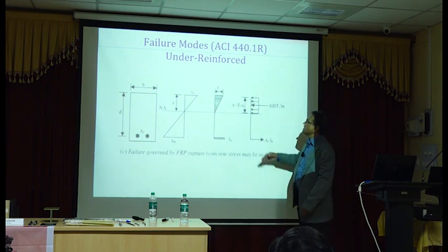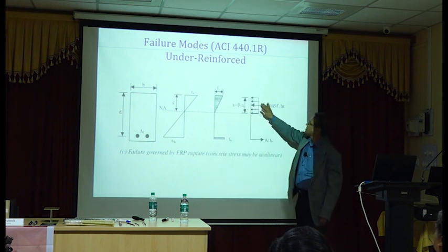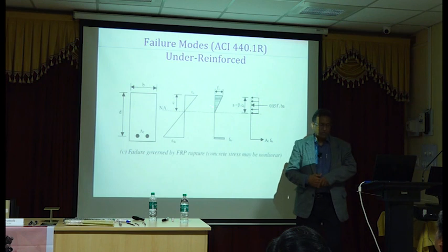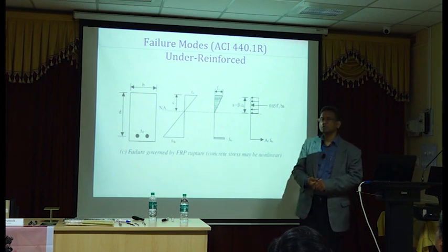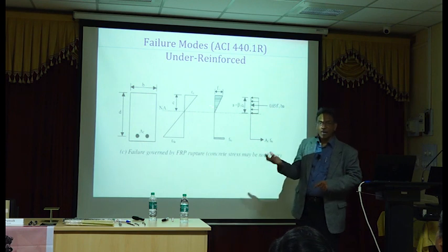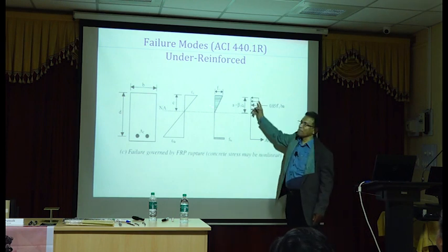So this area is not known, and therefore we cannot use a rectangular stress block. You can use a rectangular stress block only if the strain is equal to 0.003 or greater. If it is not yet 0.003 or greater, you cannot use a rectangular stress block.